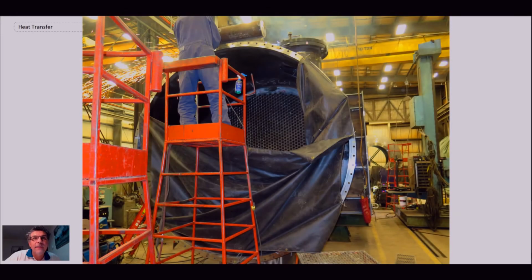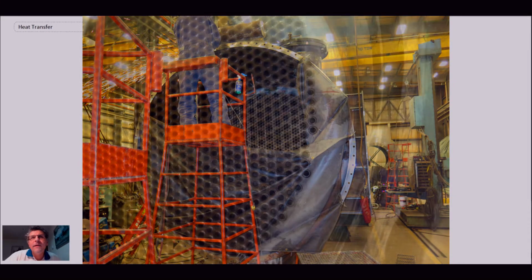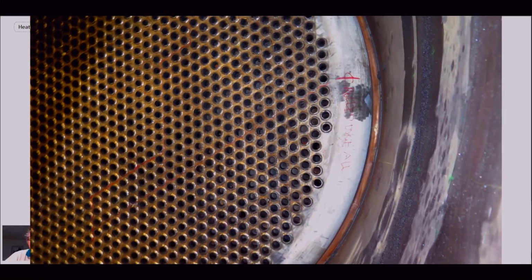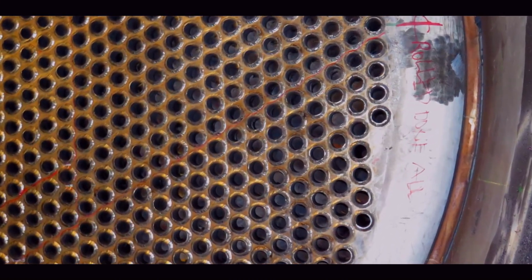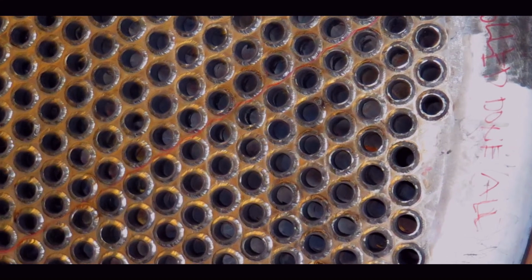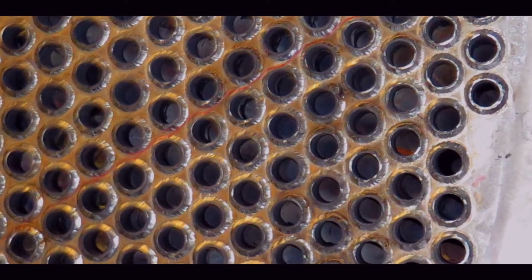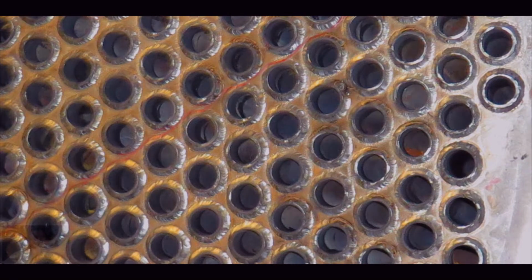And then finally, the last application that we're going to look at are very large-scale industrial condensing units. And so here we can see a picture of a condensing unit being fabricated. Sometimes it's hard to tell the difference between a condensing unit and a shell and tube heat exchanger. They're very, very big, and you've got a lot of tubes on the inside. But in this particular one, this was one where it was tube-side condensation. And so they are relatively large tubes. The tubes there, they're probably 1.5 to 2 inches in diameter. And so what is happening is you have condensation occurring within the tubes.